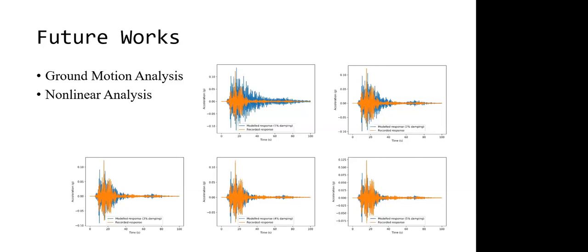And the other thing is I used all positive numbers for my regular nodes, and I was using a lot of slave nodes because I was modeling the PY curves, so I had to use zero length nodes, right? For each node I had an X direction, Y direction, and Z direction soil spring. So I created 3 additional nodes for a particular pile node. If I was keeping the same positive numbers, it was confusing. So I kept a negative number.